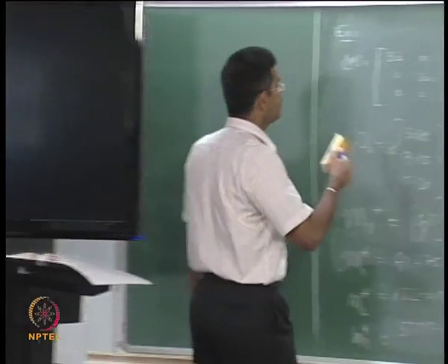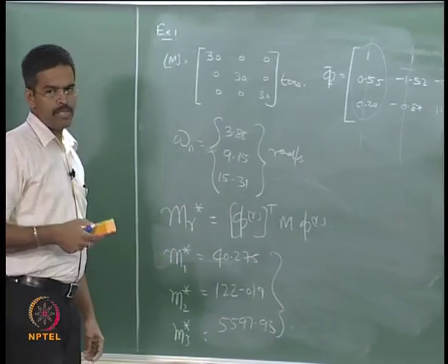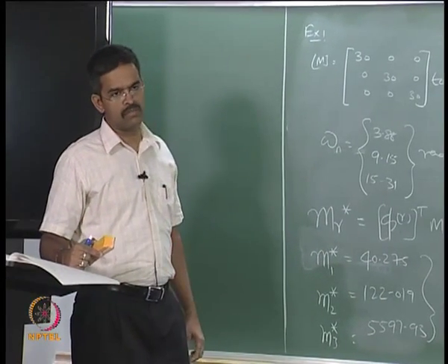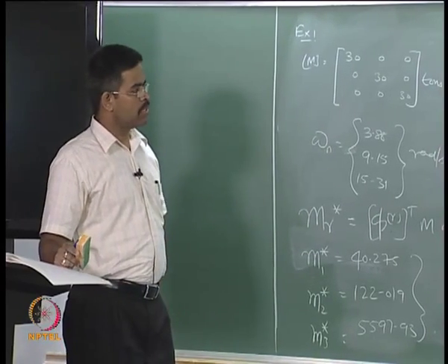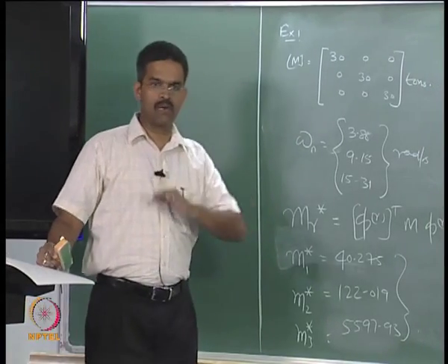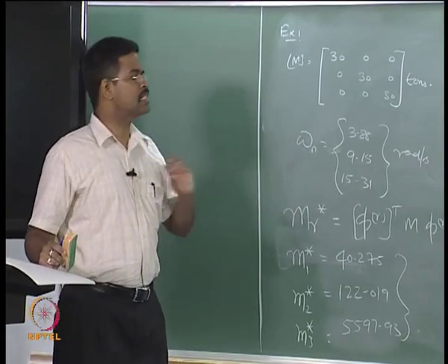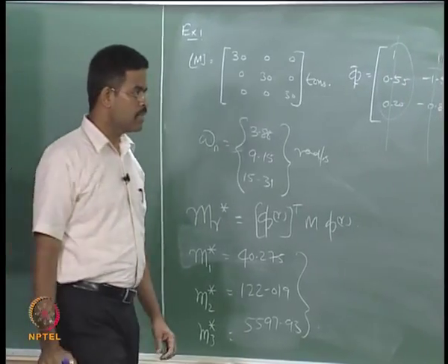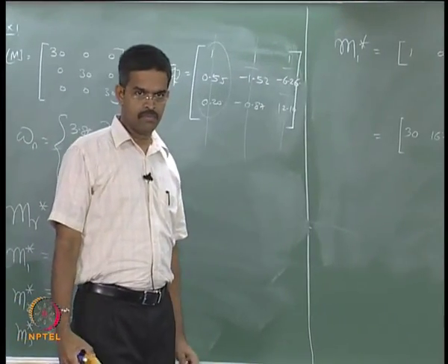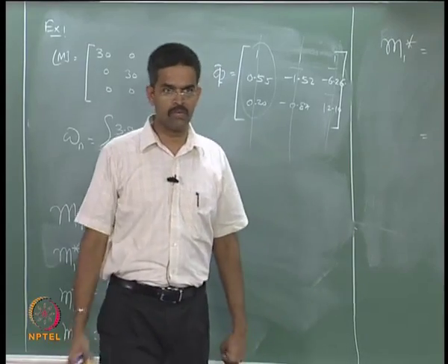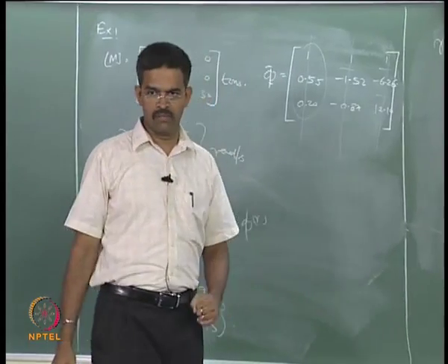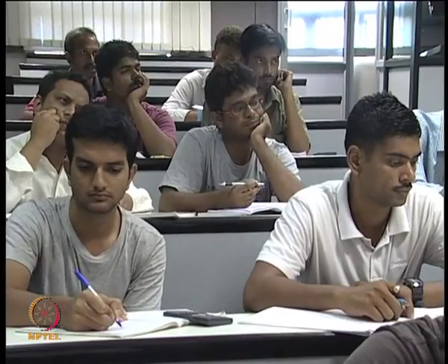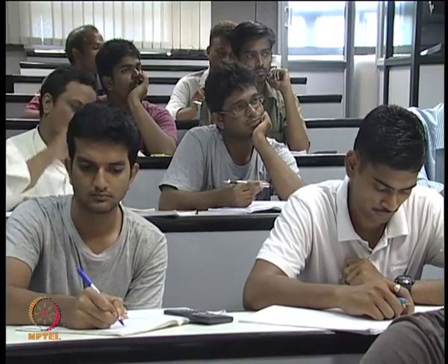Having said this, now let us see how we truncate the modes. What will be the condition for truncating the higher modes, where do we stop? Is it frequency governed or mode shape governed? What would be the effect in a nutshell in dynamics if you truncate them? Can this error be corrected, because you very well know you are creating an error by truncating the upper modes? Can you correct this error? This is called static correction. We will see that also. Remove this, then I will take up the same example and apply it from a different perspective.